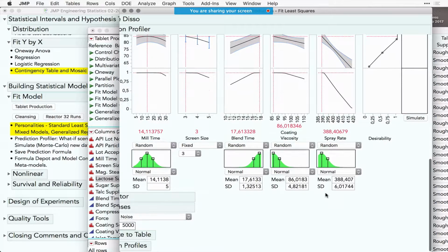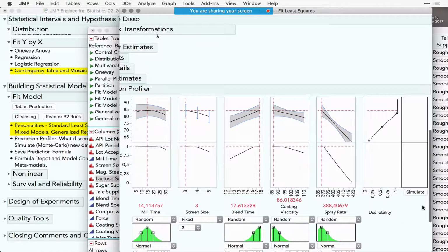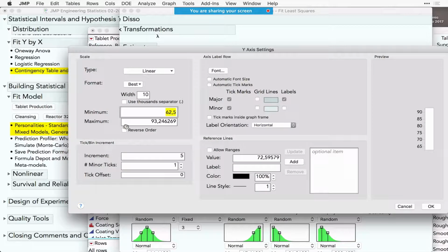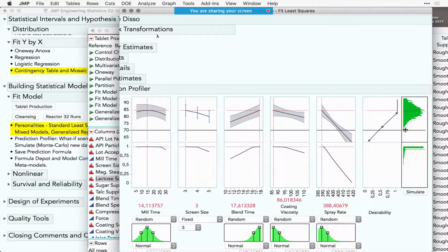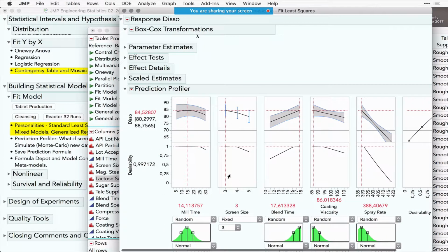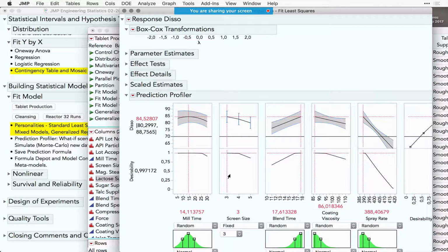You can also specify in more detail, of course. And then by Simulate, I do Monte Carlo simulation. So this does 5,000 simulations by default. And 70, that's our lower specification limit. So if you simulate, the data points down here are the out of spec data points and the problems you want to avoid and minimize.